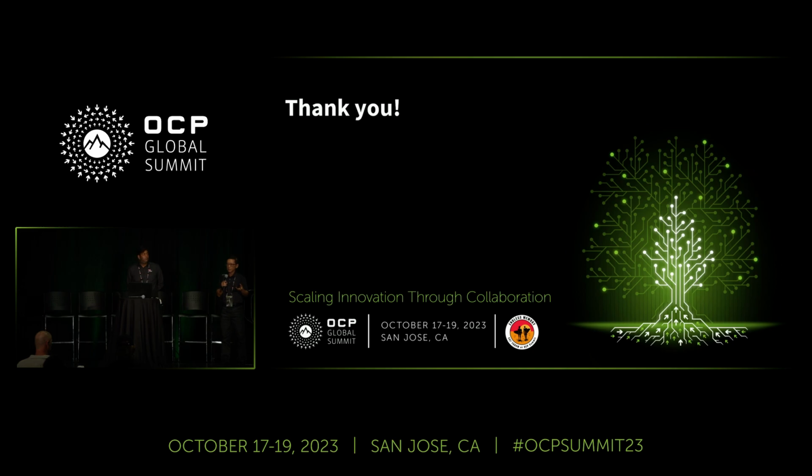But overall, I see that currently in Gen 5, especially in AI/ML systems, they do need retimers because those systems are huge. They run long traces and big backplanes and everything else. So they do require a retimer. Thanks. Thank you. Any other questions?